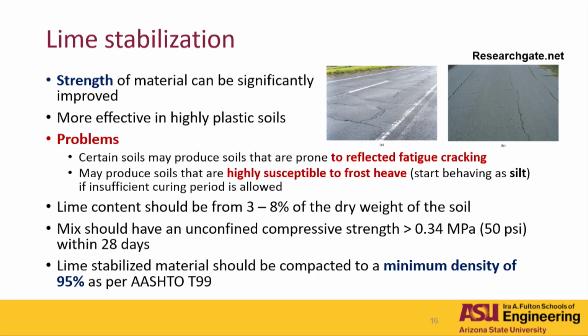Problems with lime stabilization. Certain soils have been seen to produce soils that are prone to reflective fatigue cracking, and there's been some documentation about that. It may also produce soils that are highly susceptible to frost heave. Like I said before, the soil is going to start behaving more like a silty material if you allow some water in there.